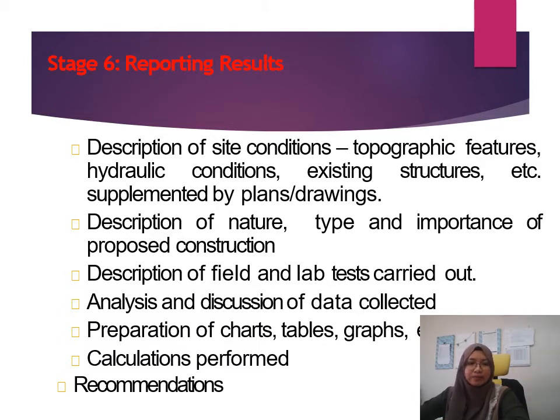The next stage is reporting the result. After you get all of the information that you want from all of the testing, either field testing or lab testing, you can describe your soil condition: what is the topography, the hydraulic condition, what is the existing structure, supported by the plans, drawings and maps that you have. Next you can describe the nature, type and importance of the proposed construction.